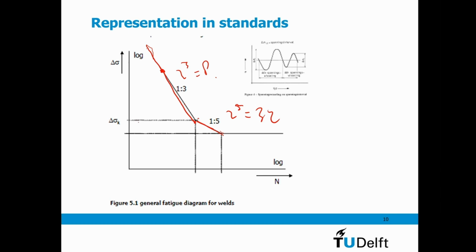And of course here, if I'm from this point to there, then I get from a fatigue life to infinite fatigue life. So depending on where I am in the curve and what curve you use in the standard, you have different effects of reduction of stress. So if you modify your design to reduce the stress variation, the consequence can be quite different.